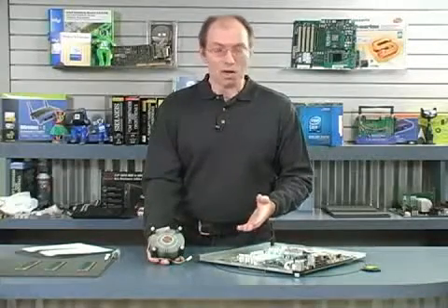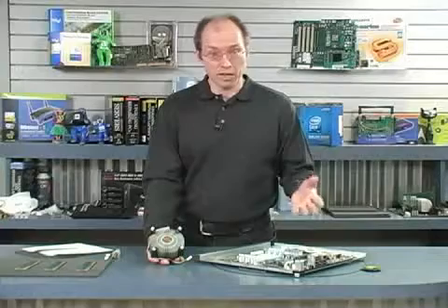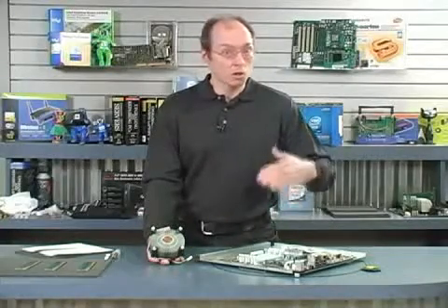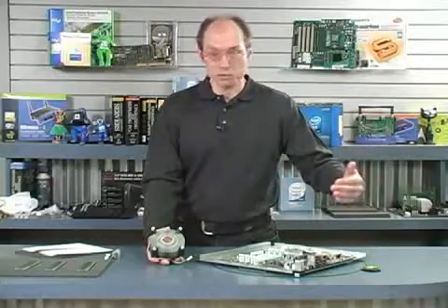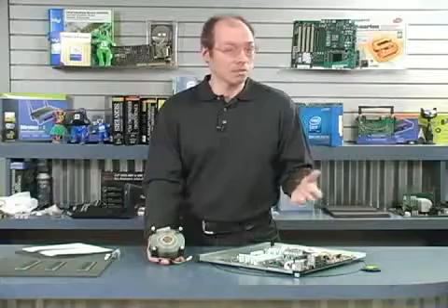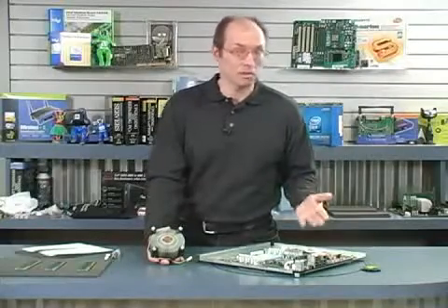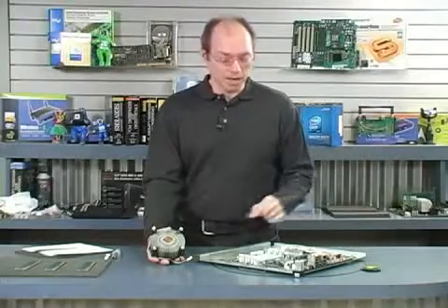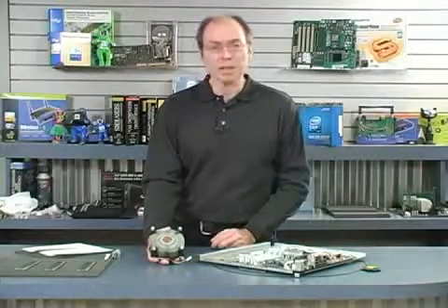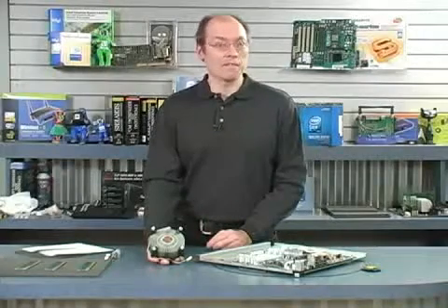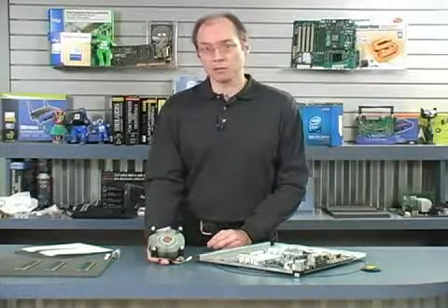What that'll cause is that in many cases the processor will overheat or not be able to run at its full speed, because modern processors don't actually overheat to the point of destruction or stopping. What they'll do is throttle themselves down. So you'll end up with a system that for some reason doesn't seem to be running as fast as it should. The real reason is you don't have a good bond between the heatsink and the top of the processor. Now, thermal interface materials come in two main types. One is called a phase change material. The other is called a grease.